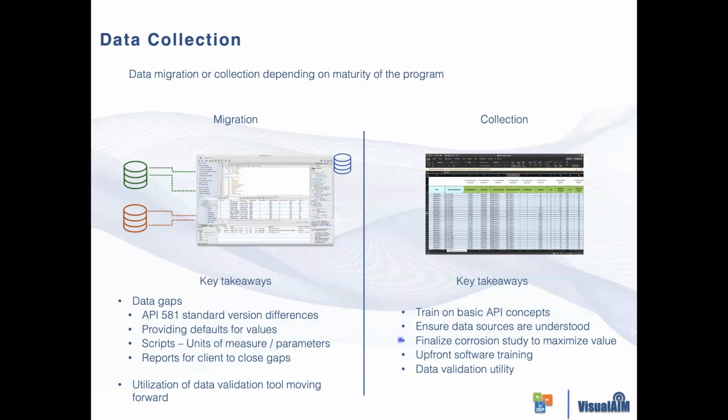With regard to the whole mechanical integrity process, you typically also perform a corrosion study, after you've defined the scope of the assets that you're going to perform the RBI study on. You typically perform a corrosion study to understand two things, basically speaking. One, the different damage mechanisms that will be present in each component, and also the different corrosion rates that would apply to these particular damage mechanisms.